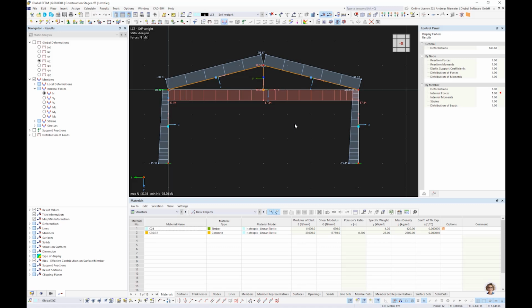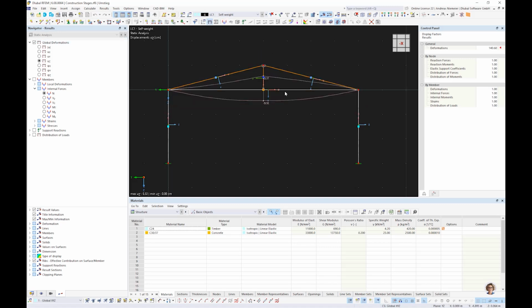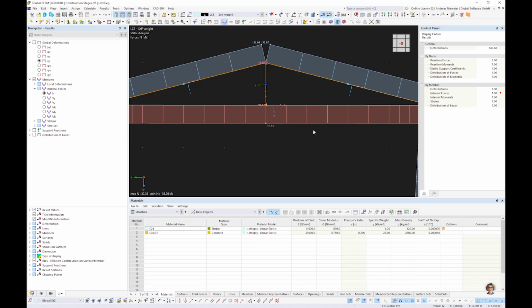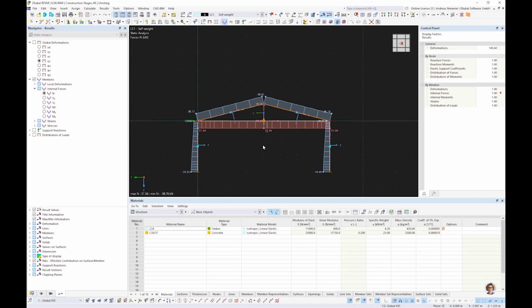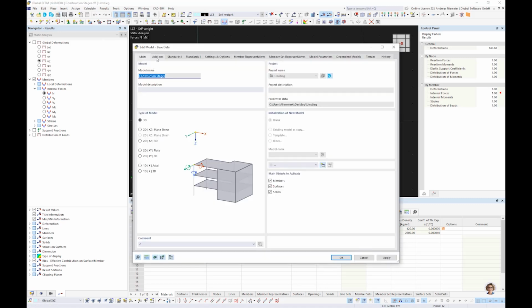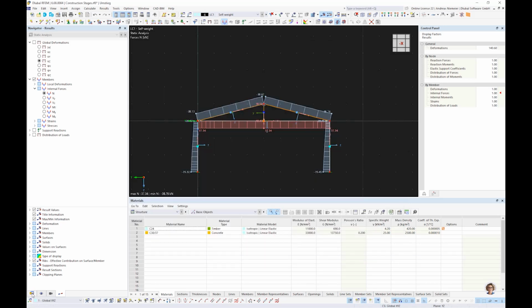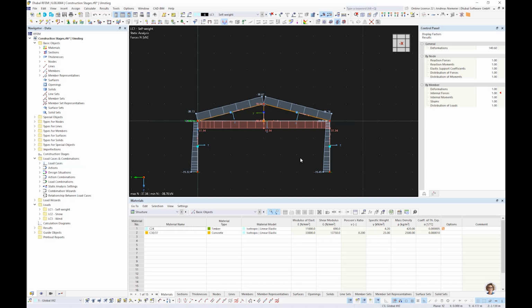Yeah, and this topic comes because if the beam is bending through, so this massive concrete beam, pulls down the roof and it acts like a truss, and the result is that this beam here, this truss beam here, have tension, and this, let's say, is a little bit unreal. And this is exactly the point where you say, I cannot model everything in 3D. I have to take care what is being first and what is being afterwards. And for this we implemented, let's say, stages. Of course, such an option exists also in the old generation, but it was really restricted only according third order large deformation analysis. Now it's opened, it's completely worked in the program and opened for all calculation theories.